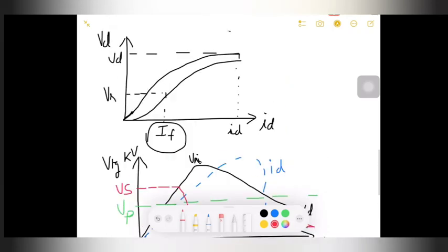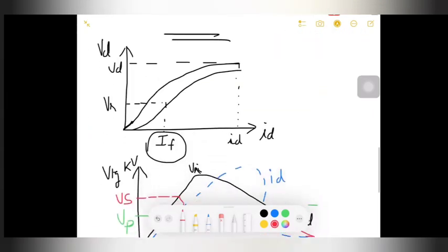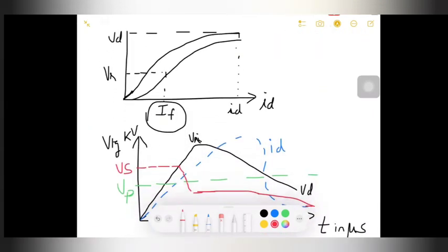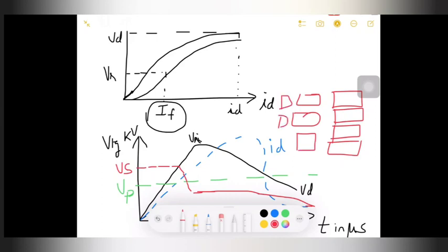Here in the surge arrestor, we will be having a nonlinear resistor element which is made up of silicon carbide or any other material, and it will be of the stack type. So the resistor will be in the form of stacks, a block of resistor one over the other. Usually it will be two or three sections of this block, nonlinear resistor blocks.